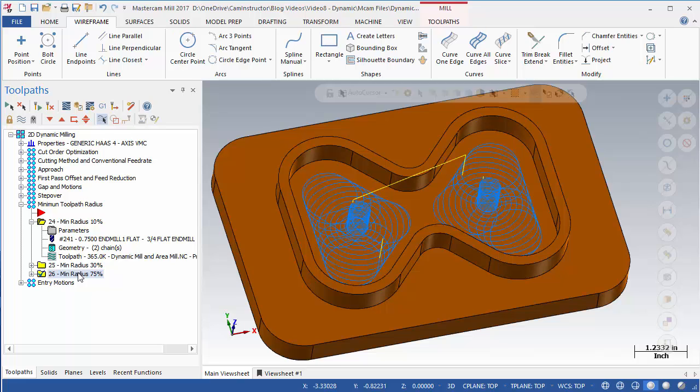This is an extreme example, but as you approach a corner that is very close in the radius to the cutter that is being used, you start to increase the angle of the engagement of the cutter. High engagement angles on the cutter can be damaging when high-speed machining is being done. More about the cutter engagement angles will be covered in a future video.